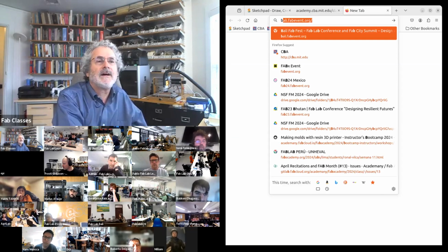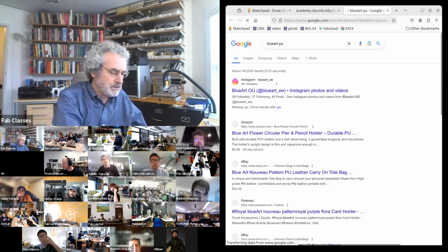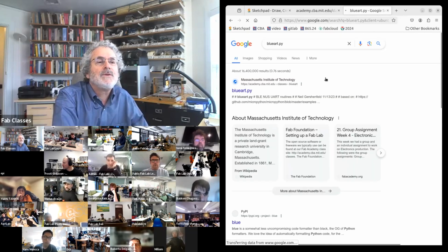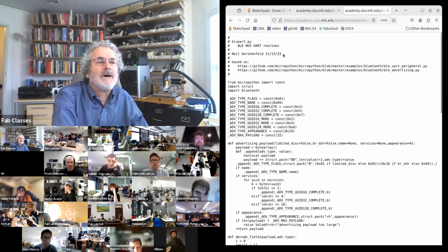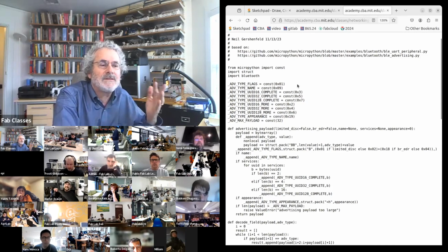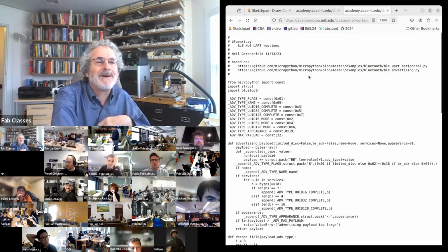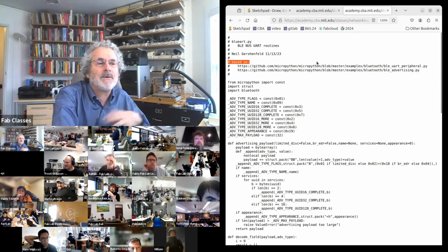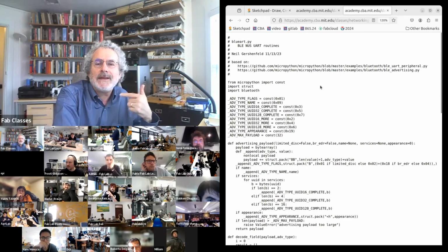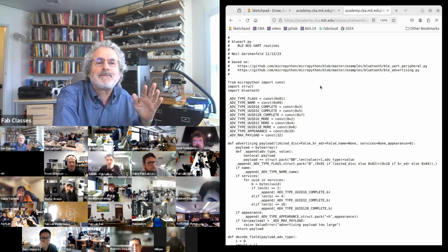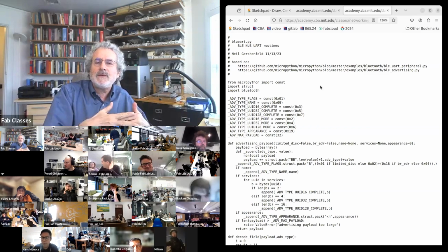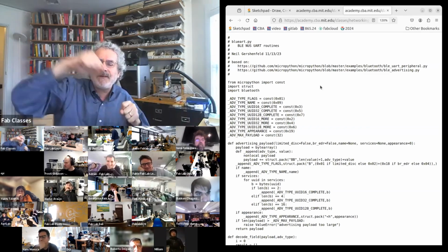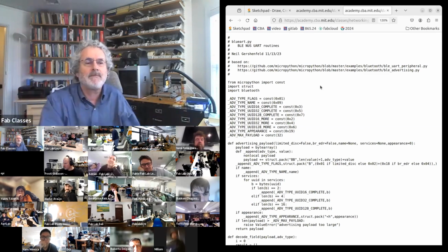This is using a particular Bluetooth profile, Blue Art. Oh, it's actually linking back to me. Oh, sorry, I forgot this is something I wrote. But this is something I wrote based on these examples, but I combined them. This is implementing a UART. We talked about UARTs when we talked about sending and receiving messages over wires. This is implementing a UART over Bluetooth. So it's as if we have a wire going through space. You just put bytes in and bytes come out.